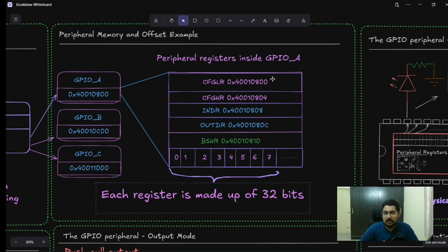But you should understand that from the point of view of a programmer, that's all a peripheral really is in the memory mapped scheme. It's just a bunch of memory, and if you change that memory, you're fundamentally changing something about the peripheral. We'll get into the details, but just understand that every peripheral is just a grouping of certain registers from a programmer's point of view.